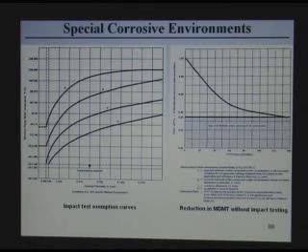Of course, if you are working with low actual stress, and the ratio of the stress divided by allowable stress for the design conditions is, say, 0.6, you get a factor, and you can go 40 degrees below this curve.